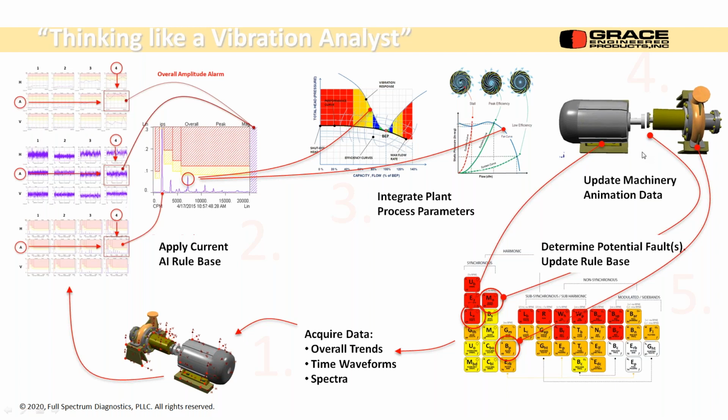There's a way that we're working on to sync all the clocks so that they all capture data exactly simultaneously and we get a good phase measurement. If that turns out, we can animate something like that and get a rough animation, but something that's going to tell us how the machine's moving, and that's part of this process to help us figure the underlying faults.